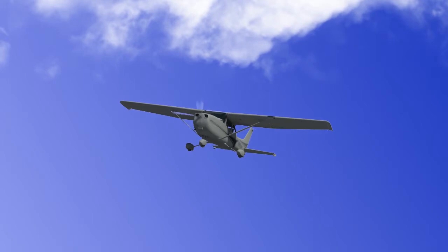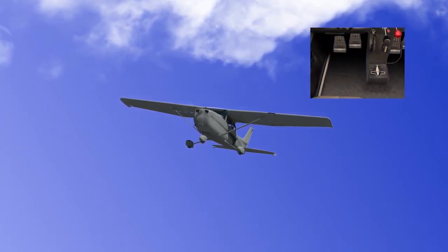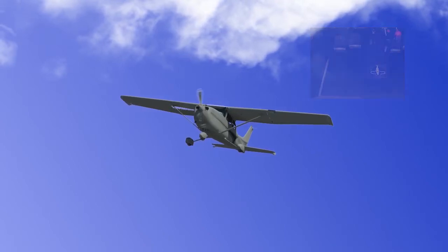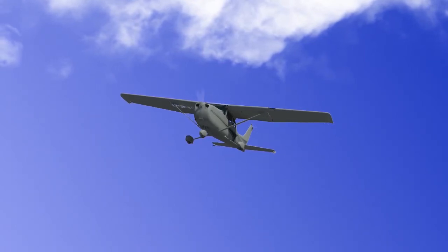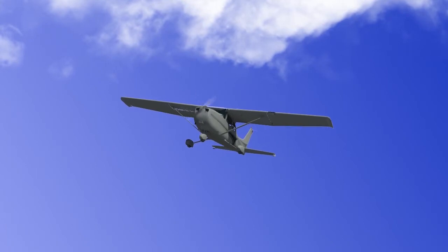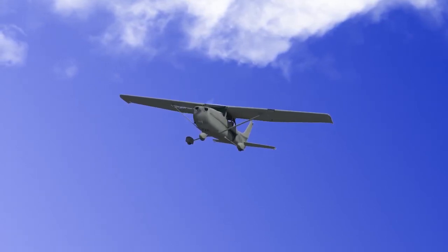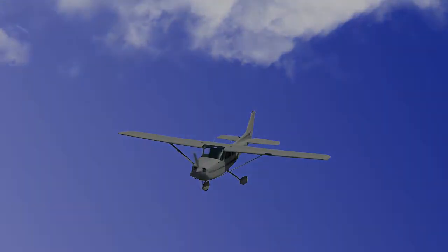During this phase, it will be important that you maintain your heading by the use of rudder control, as the plane will want to rotate to one side or the other. As the airplane reaches critical angle of attack, the stall warning horn will most likely be buzzing and you will feel a vibration or buffeting. Once this occurs, you will immediately lower the nose while maintaining your heading and allow the airplane to gain airspeed without losing altitude.